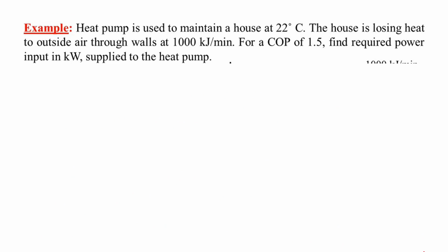Now we can go to the second problem. A heat pump is used to maintain a house at 20 degrees Celsius. The house is losing heat to outside air through the wall at 100 kilojoule per minute. For a COP, coefficient of performance, of 1.5, find the required power input in kilowatt supplied to the heat pump.